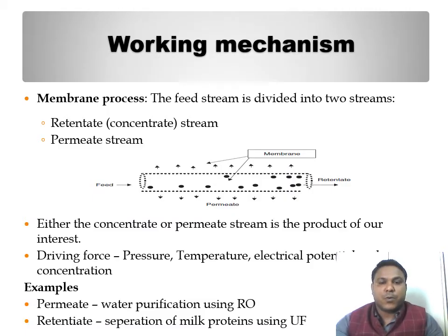Membrane process covers a group of separation processes in which the characteristics of a membrane, that is porosity, selectivity, and electric charge, are used to separate the components of a solution or a suspension. In this process, the feed stream is separated into two: the fraction that permeates through the membrane, called the permeate, and the fraction containing the components that have not been transported through the membrane, usually called the retentate or concentrate. The size of the component to be separated and the nature and magnitude of the driving force provide criteria for classification of the membrane separation processes.